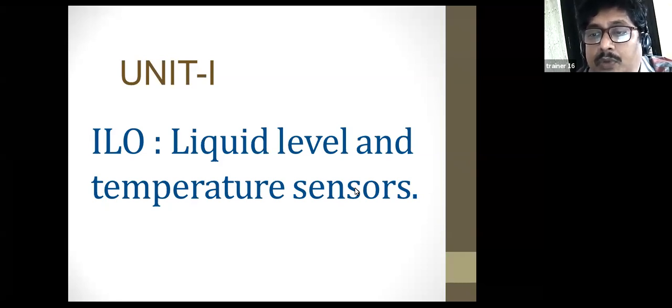And then next we discussed the capsule and also the bellows gauge. A capsule is the combination of two corrugated diaphragms. For the bellows gauge, we already explained one example. It is connected with the core in an LVDT, linear variable differential transformer. By applying the pressure, the core moves from bottom to top, and similarly from top to bottom.